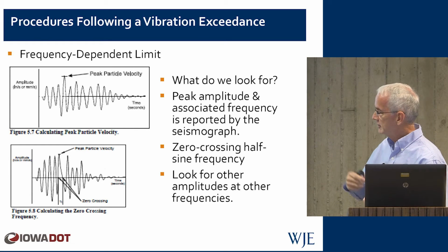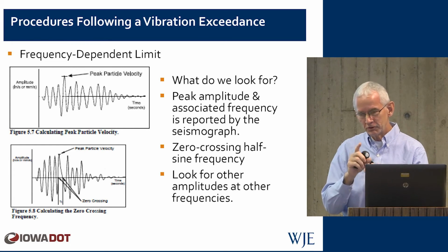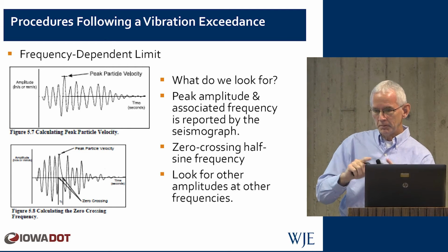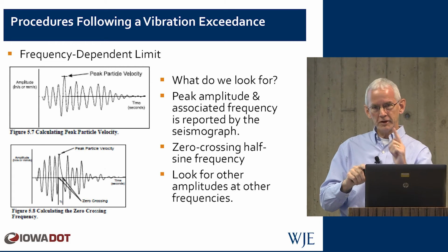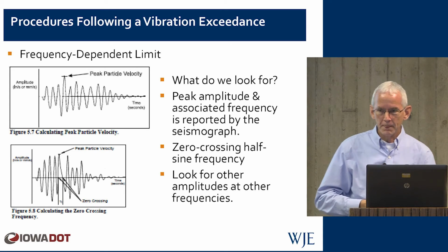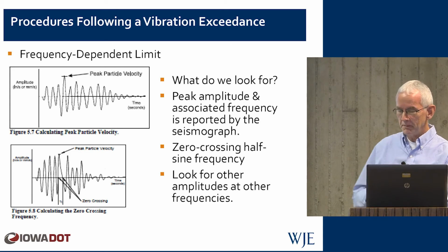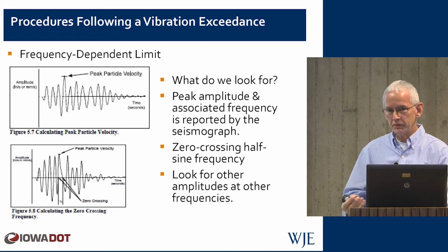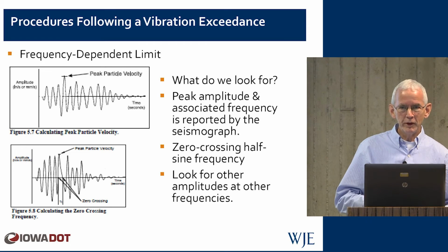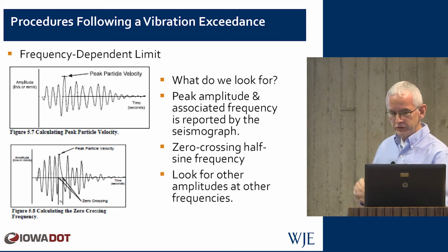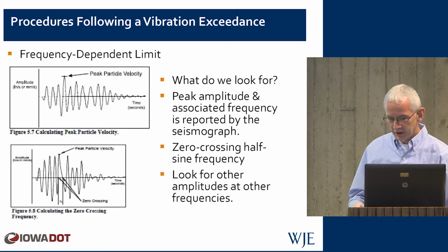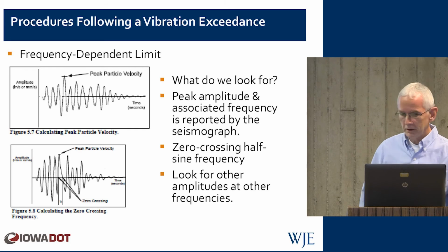And what happens with that is sometimes you have a high frequency vibration which produces a maximum but is riding on top of a low frequency, and it might not cross 0 till several cycles before and several cycles after that peak. And it may show as a low frequency, it may show as a high frequency. You don't really know for sure how the software is going to interpret that waveform, because it's all done just digitally through a relatively simple mathematic process, and it doesn't go back and look for underlying frequencies.